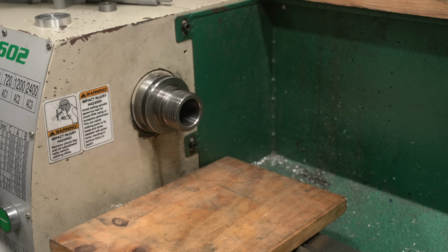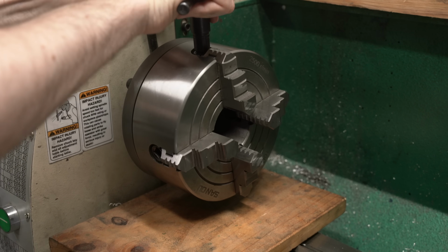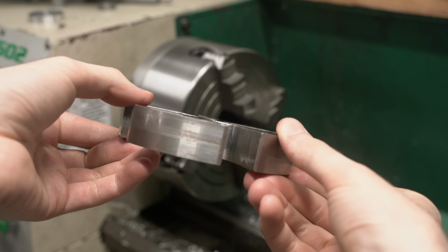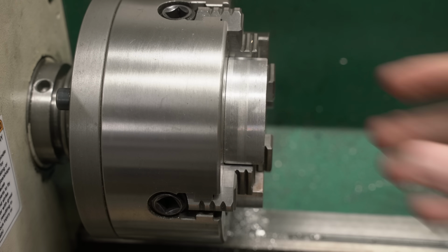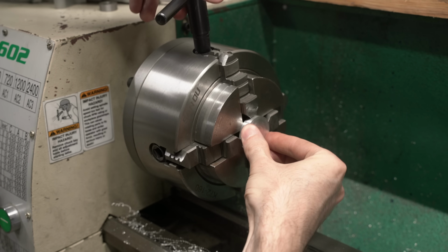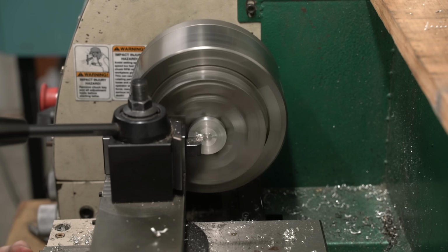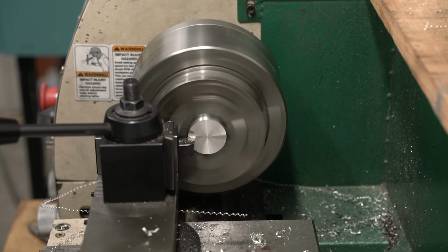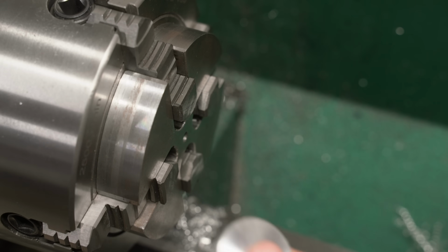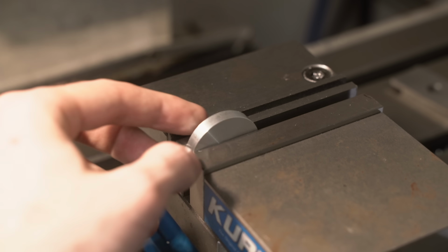This gives me an excuse to use one of my favorite lathe tools. This thing is called a lathe spider. It slides onto my 4-jaw chuck, allowing us to grip thin parts like this and ensuring that the faces are perfectly square to the chuck. Now we can cut the second face and bring the disc to its proper thickness. Now I transfer the disc to the milling machine.